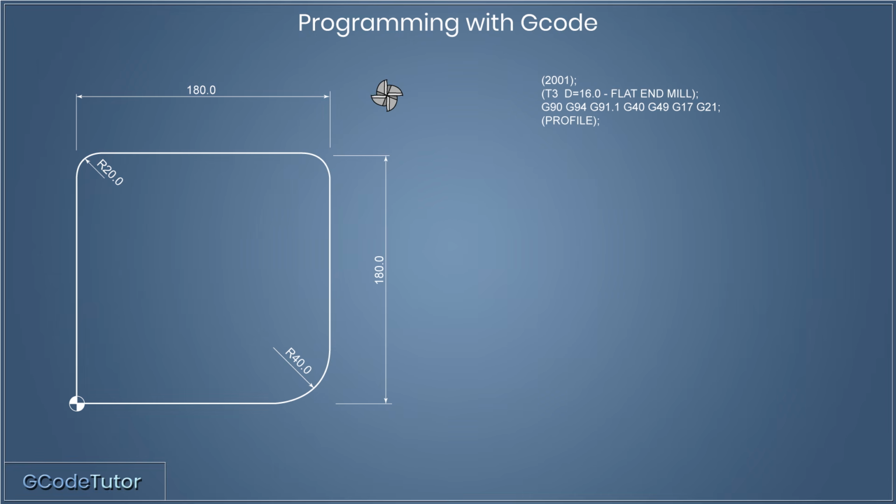Now with the machine set up, we can start writing our program to make this shape. First I'm adding an operator's note to describe this operation. I'm just going to call this profile. Sometimes we can add tooling information here, but where we're only using one tool, that information was added at the beginning of the program. So this operator's note just tells the operator which block of the program we are about to run.